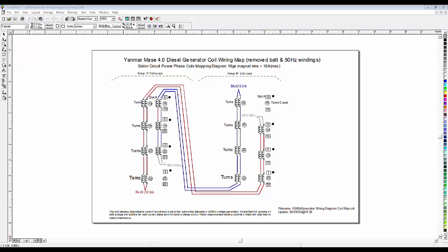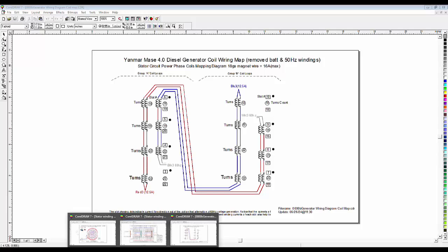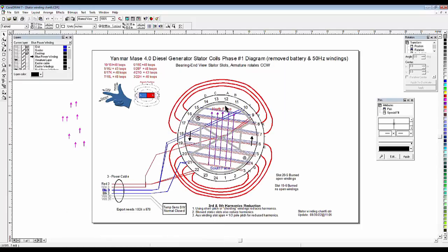So why were these 8 slots over here labeled improperly with the dot? Well, the reason is that's a physical orientation of how the current would flow when I had it wrong. The reason it was wrong is because if you take a look at the rotor, you notice you've got a north face and a south face. So the 2 faces have different results on the windings they're cutting. So therefore that reverses what's happening in the opposite set of windings, the opposite set of 4 or 3 windings, whichever the case may be.